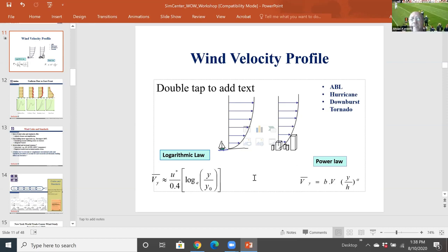Well, large offshore structures will be somewhere even on the left of this. There the profile would be a little bit more fatter than this one. Like typically 0.1 would be the exponent alpha for that one. By the time you reach the coast or very near the coast, it might be 0.12, 0.13. So the profile for offshore structures is totally a different area because you have interaction with waves also. So that's a little bit more complex. But if you just want to use basic design procedures, the profile would be even, I would say, more.